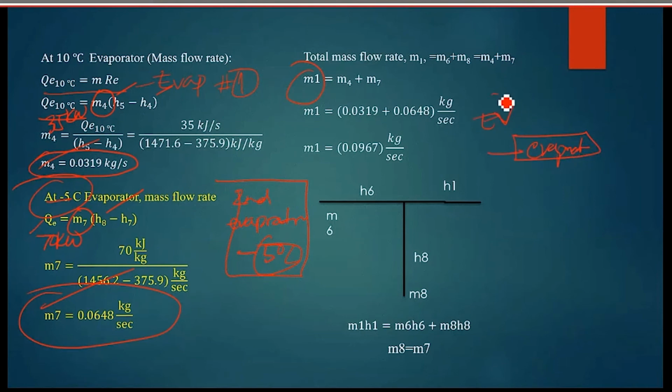This is the expansion valve at a lower pressure, then the liquid evaporates, because the compressor only needs a gaseous state. You cannot put a liquid in the compressor. It will damage the crankcase and everything. The compressor needs gas or vapor only.